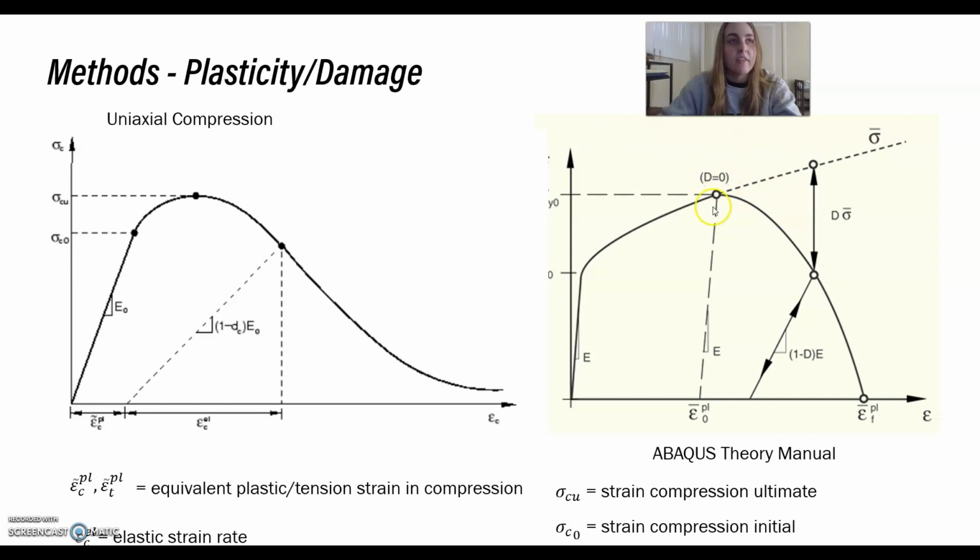In the second graph, you can see this dotted line. This trend would have been assumed to follow the dotted line if it were just plasticity and no damage occurring. But because there is damage occurring, as it's a quasi-brittle material, it begins to descend. The difference between the dotted line and the real trend that comes from damage is where this accumulation begins to become discernible.